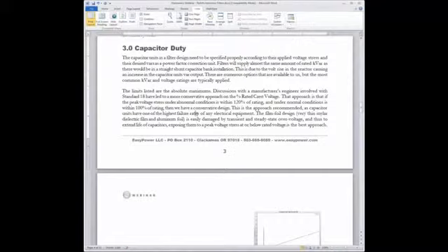Or you can do it in per unit. You could do it in percent. But we need to make sure that we have taken that into consideration. And again, my recommendation for you is that for normal operation, non-contingency conditions, you operate at 100% to have a conservative design. And for your contingency conditions, you're allowed to go up to 120%. We could probably break into half an hour of questions about how long that should really be, but just use your best engineering judgment to try to come up with all of your normal conditions having 100%.